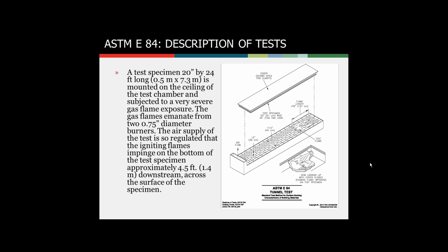And the material is left in there for 24 hours. At that point, you would empty the vat or the tub that the material is leaching in, and then replace the water with 20 degrees centigrade water again. You do this until the 72 hours is up. So it's 3 changes of the water at 24-hour points.